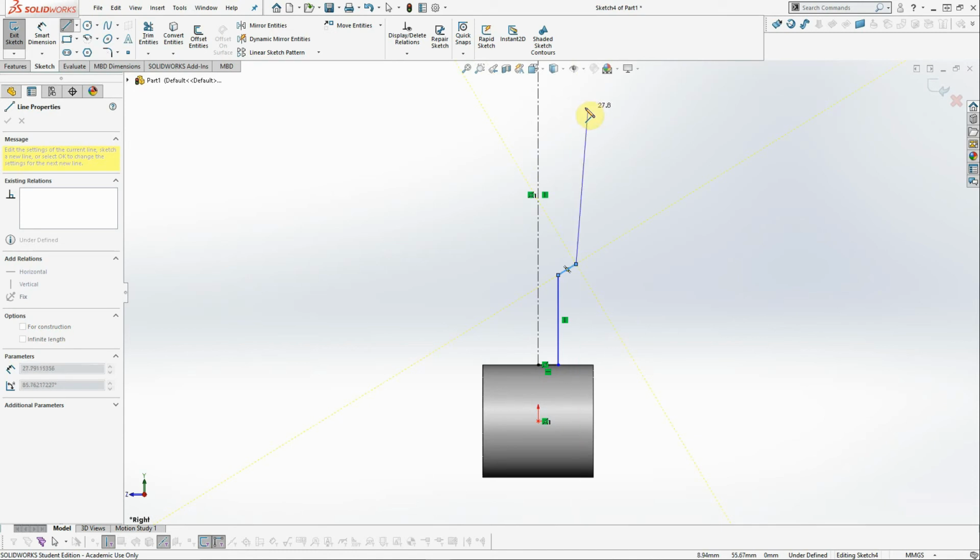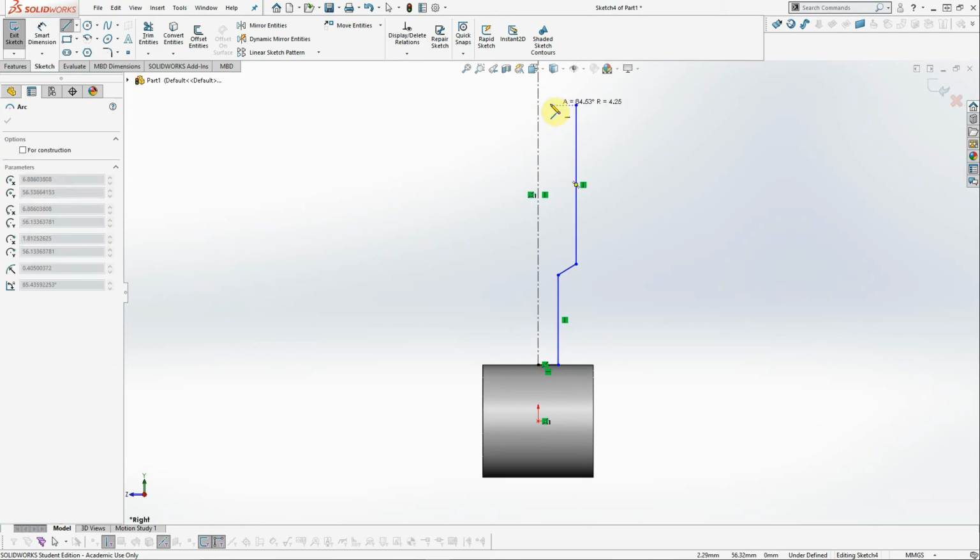Yeah, I think that's right. And I want this vertical, and I want another line horizontal. Now I follow the horizontal line and go over. When the center line is highlighted and I have my dotted horizontal lines, that means if I click here, the end point will be right on the center line, and it'll be horizontal to the previous point, which is what I want.